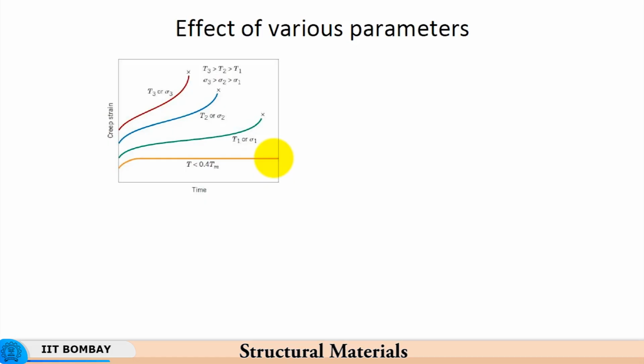The grain boundaries are the ones which were strong at low temperatures, but now the grain boundaries tend to become weaker because the temperature is rising. So, part of the reason why you have creep strain is because of diffusion taking place along the grain boundaries, due to which you have grain rotation and grain boundary sliding, and plus added to that some dislocation movement also.